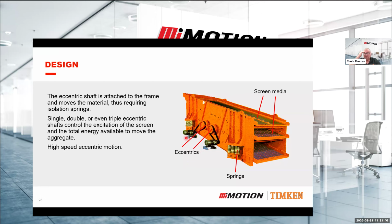So again, there's plenty of opportunities there for bearings, and they have to be of a particular specification. That's the key thing on a vibrating application. You'll also see ones that have gearboxes sitting on top, the vibrating screen mechanisms they call them, and they basically just bolt a number of them on top of the screen. Can be one box, can be 2 or 3 boxes, depending on the application and the weight of the product that they're actually trying to screen as well.